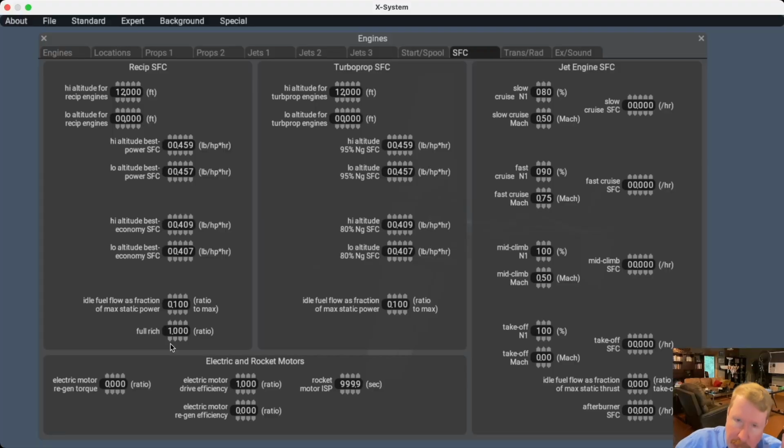And so they would actually enter more fuel than standard. They might have had like 1.5 here or something like that, or maybe it wasn't quite that bad. But they would actually burn more fuel than normal. Well, they wouldn't even burn it, but they'd send in more fuel than normal, and the fuel would evaporate and cool the engine. And so they actually used extra fuel for cooling. And boy, that is such a weak, pathetic little hack, isn't it?